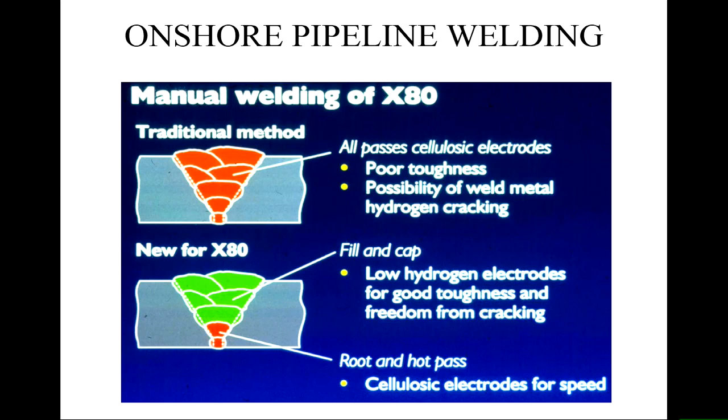For various reasons. One, the pipe is thinner because the X80 has higher strength. It can actually, for a given pipe diameter, therefore put slightly higher gas volumes through. It's quicker to weld because the pipe is thinner. At least it would be if you were comparing things directly, but people will always make comparisons with very inappropriate older designs when they do that. It's not actually that much quicker to weld. But we have better welding procedures to cope with it.